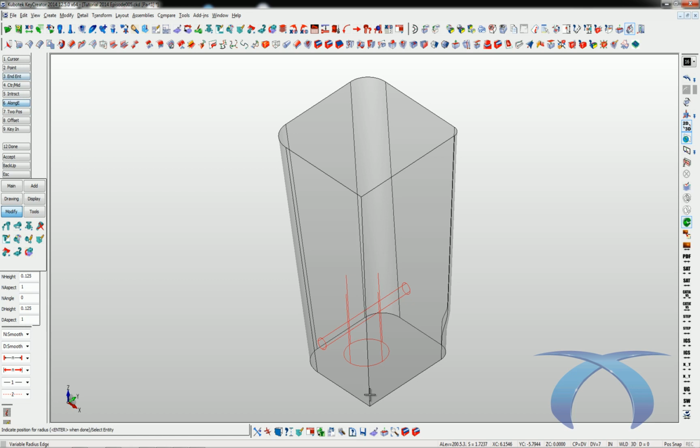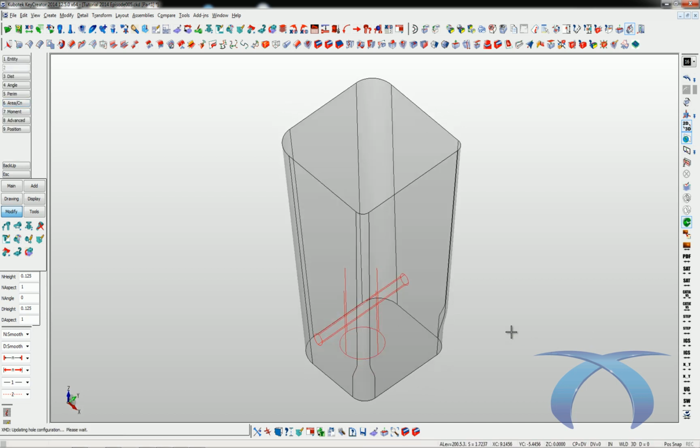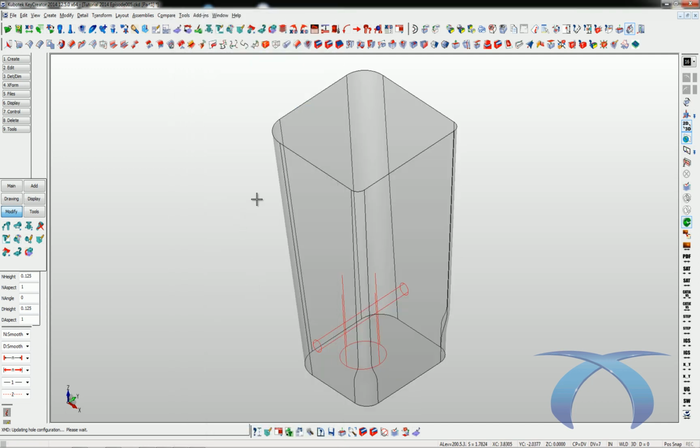We'll do the same thing over here. We'll go along it as well, 1/2 inch. And then we'll go along at 1 inch for that 200 thou. So now I have that taper. It's the same all the way through. Okay. So what I'm going to do here is I'm going to copy this solid to another level. And that way what I can do is I'll use that bit of solid to actually pull the pocket out